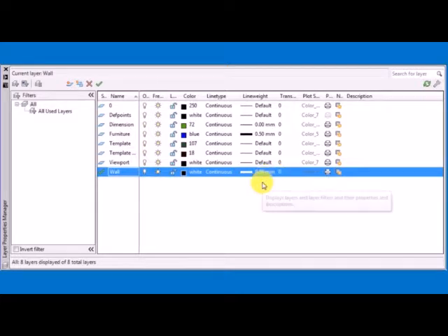And you know, the exercise from the textbook doesn't have line weights. And so I will enable some line weights. It makes the drawings look better. But they're asking us for a stair riser, and that color is going to be blue. So I'll say new layer.